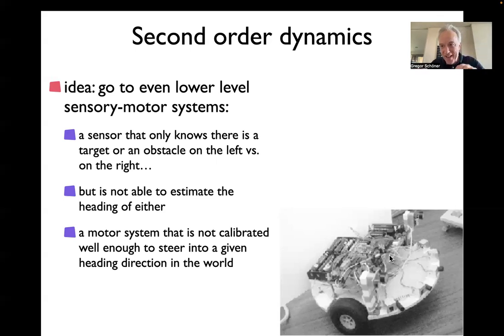So we took that. This is just the batteries and these cables. We made a little circuit to condition the sensor signals. Here you see the sensors. This thing here is the light emitting diode, and this little rubber around it gives it focus, so that the light goes only in certain directions. And this is the detector, which detects infrared light. There are only 5 such distance sensors on this robot, and we operate each one in sequence, so that there's no interference between the different ones, because the light could also be reflected in other directions.